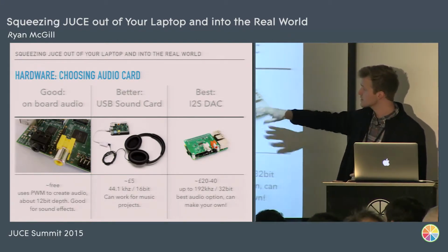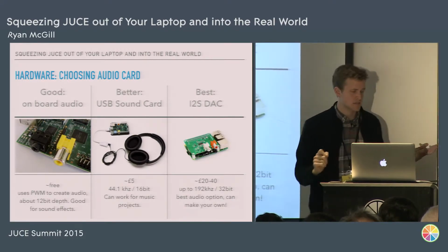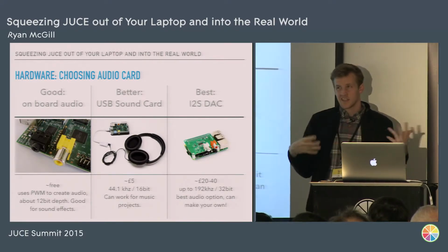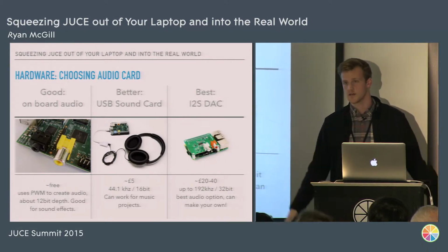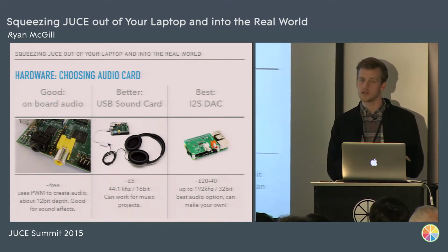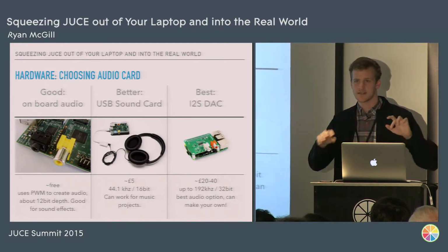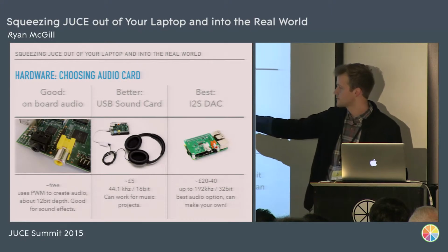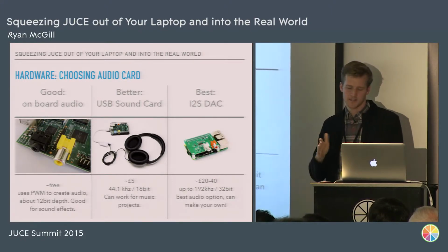And basically, this uses a digital protocol known as I2S, which is nothing really different from any sort of real serial communication protocol. There's books on this stuff, so I'm not going to go too in depth with it, but basically you can just Google Beagle or Raspberry Pi I2S DAC, and there are manufacturers that make these shields or these little boards that are just kind of plug and play.